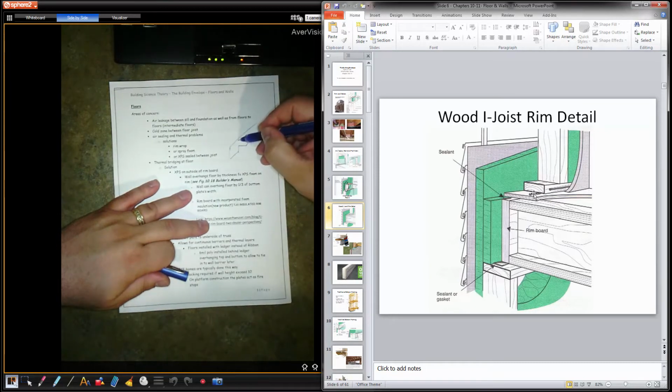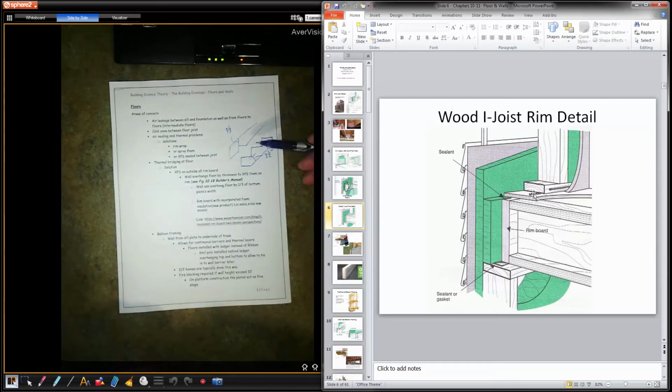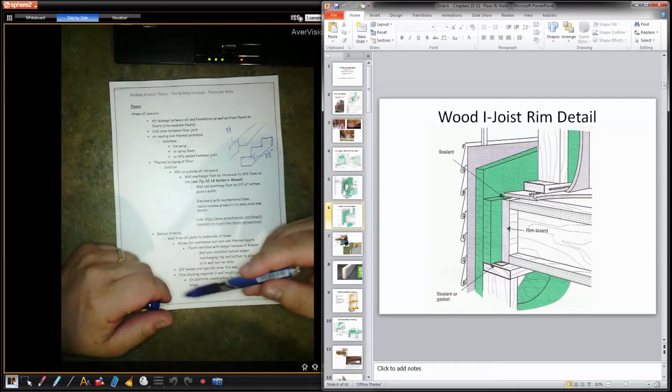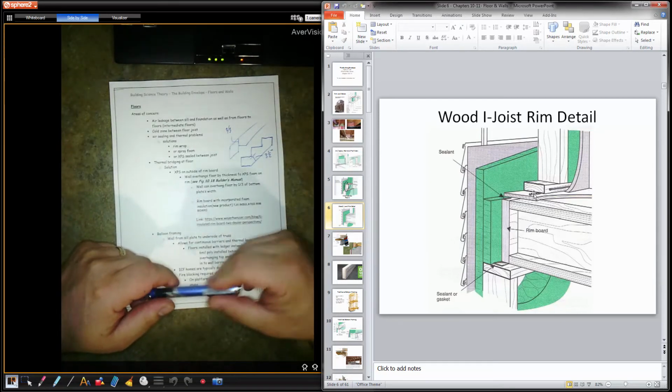The meat here left over has to be 2/3 of that material. If you're cutting a set of stringers for a set of stairs, same kind of deal there. There's a minimum here, which is 3.5, which is based off of 2/3 of the material. Okay? 2/3 of the material.